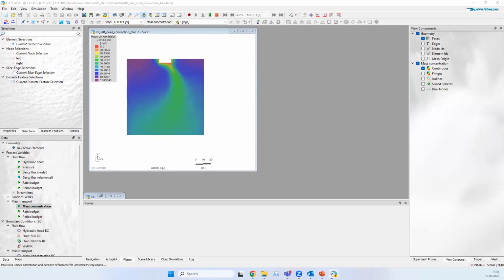Is it correct if I assign a first type hydraulic head time series changing at the coastal boundary to simulate the sea level rise? It is correct, but you need to remember that FEFLOW works with freshwater equivalent, so your heads need to be corrected by density.